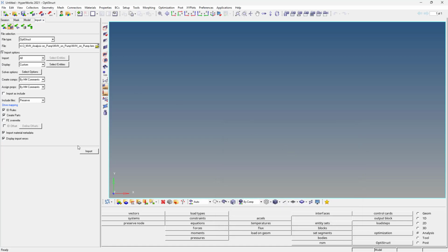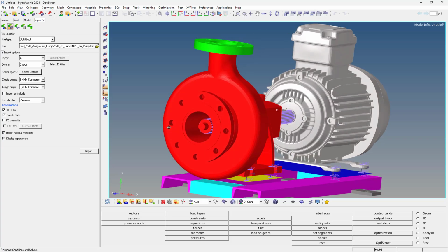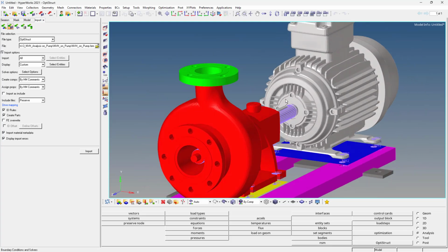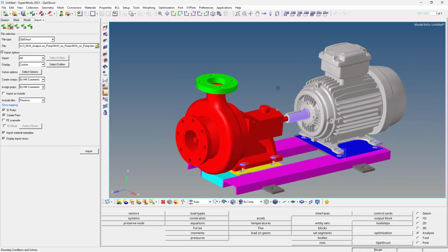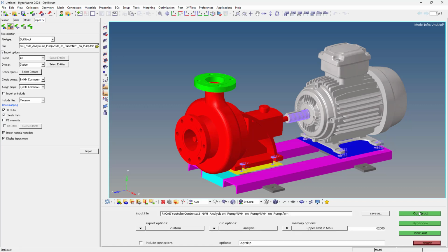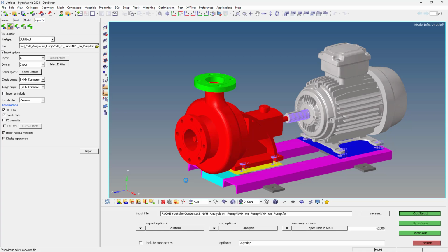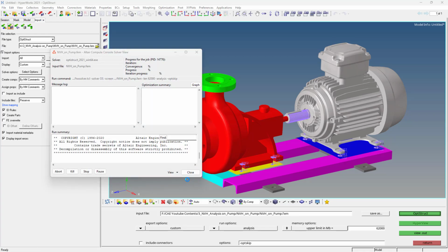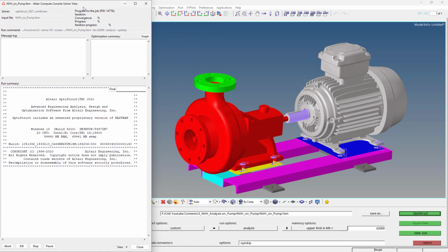Okay, open it. While opening, you might get some warnings and errors. So if it is not, then your model is fine. Good to go with this. See, everything is fine. So now just go to analysis bottom, just select the OptiStruct and type as analysis. Click on OptiStruct, just replace it once, and then the solver will start to run by using the compute console solver. Yeah, I can just keep it here, so it will take some time.